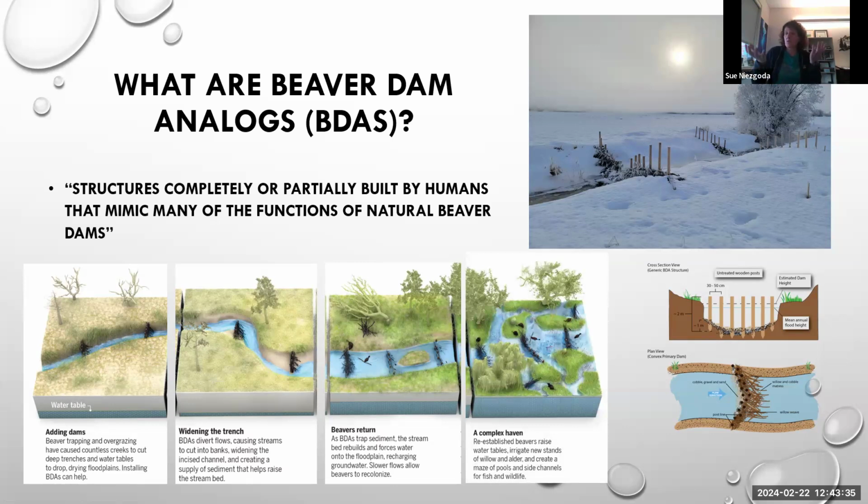And as it does raise that channel bed back up with that sediment aggradation, the hope is that the groundwater table will also be raised back up and go from draining away from the vegetation in the floodplain to really refeeding the vegetation, to give it the water supply it needs to improve the riparian zone as well, right? Or maybe you then also come in and do some riparian vegetation plantings that that water can then feed, to help grow.